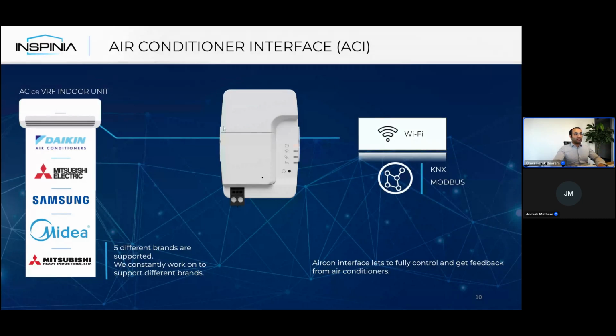After that, this module's protocol will be an add-on's protocol. I mean, when we put a KNX add-on here, under this cover, in the add-on port, this air conditioning interface will be, for example, a Daikin KNX air conditioning interface, or a Samsung KNX or Modbus air conditioning interface.